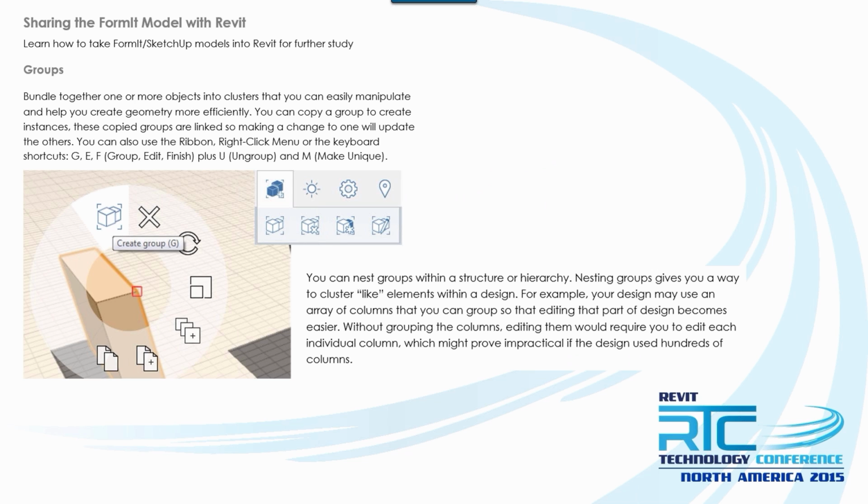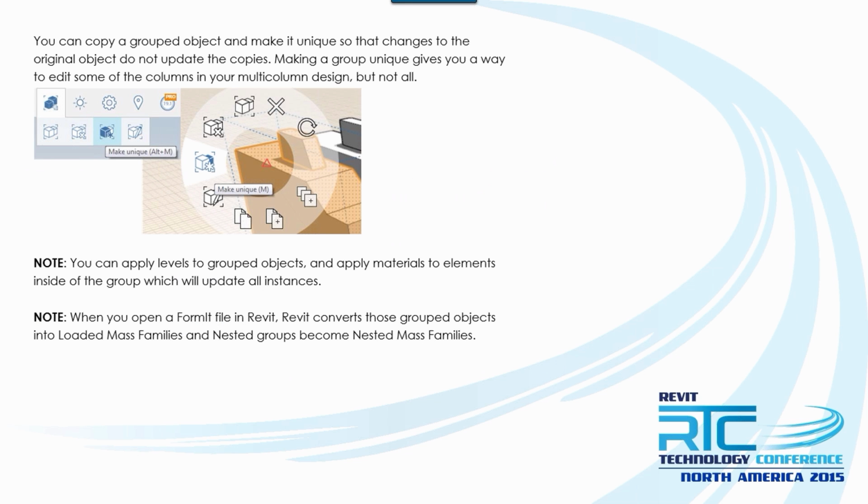The other thing that you have to understand is that anything that you create as a group ultimately turns into a family once it gets into Revit, and that's a major little trick. One of the cool things that a lot of people were registering when I was at RTC this year was placeholders. A lot of them said, oh man, so I can just build a bunch of little boxes or cones or whatever, name that a certain name, and make that, I don't know, the furniture category. And then once it got into Revit, you could very easily grab all that and swap it out right to the family that it needs to be. Yep. So a lot of people were really digging that idea.